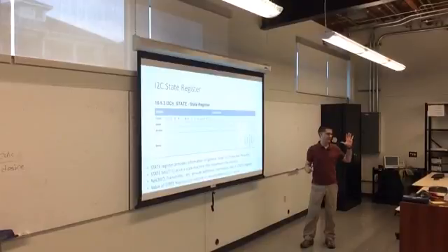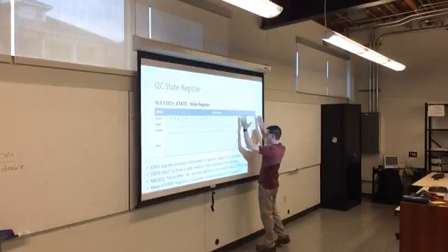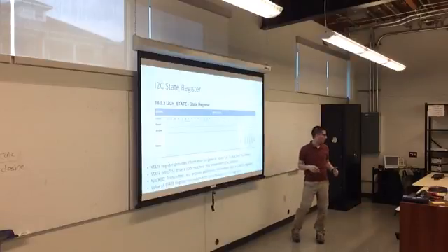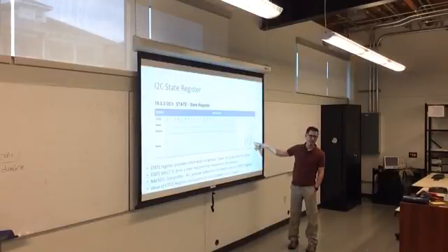There is a lot in here: whether the bus is busy or not, whether you are the master or not, whether you are actually transmitting or not, whether or not you have been NACKed during this transaction, whether the bus is being held. If you're doing stuff, you are holding the bus.